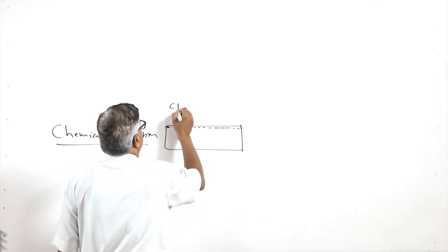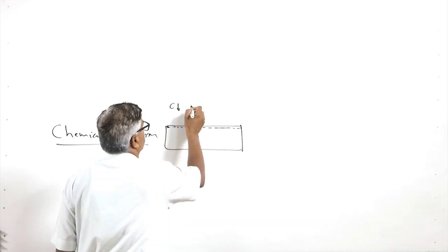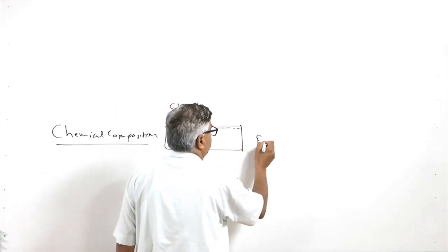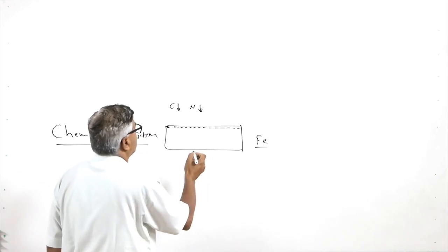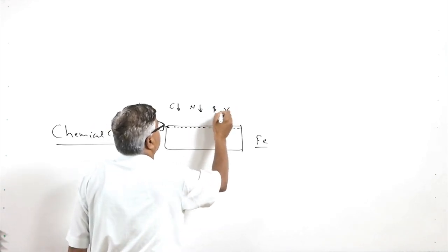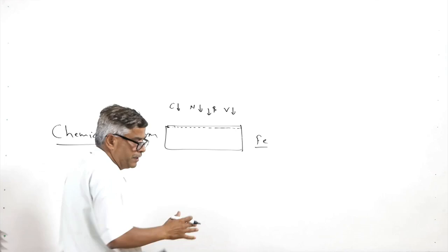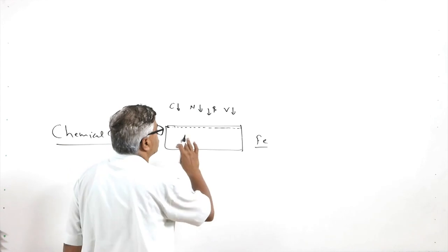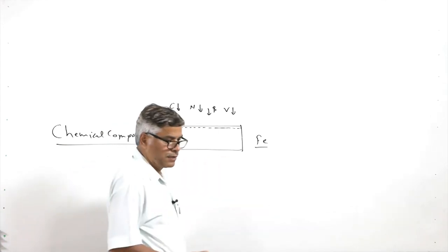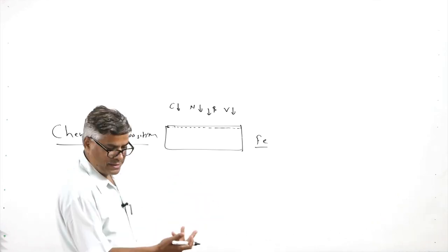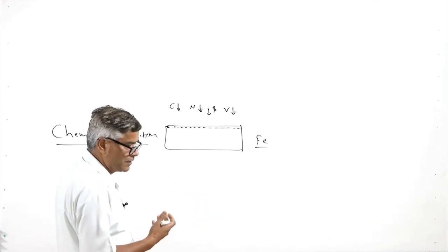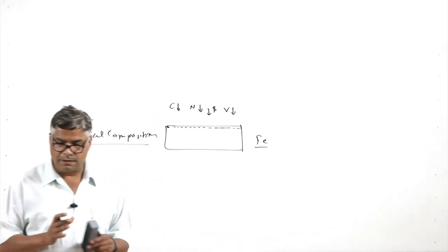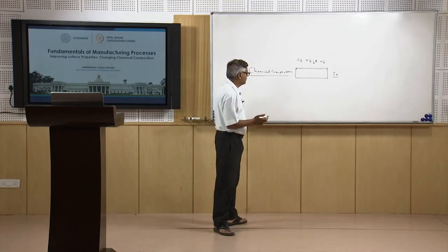Normally certain alloying elements help to improve the properties of the surfaces, mostly in the ferrous systems, like introducing carbon or nitrogen or boron or vanadium. All these help in the formation of phases and compounds at the surface layers. So the properties, especially hardness and wear resistance, improve, and sometimes favorable residual stresses are also produced, which help in improving the properties of the components being made by the manufacturing processes.